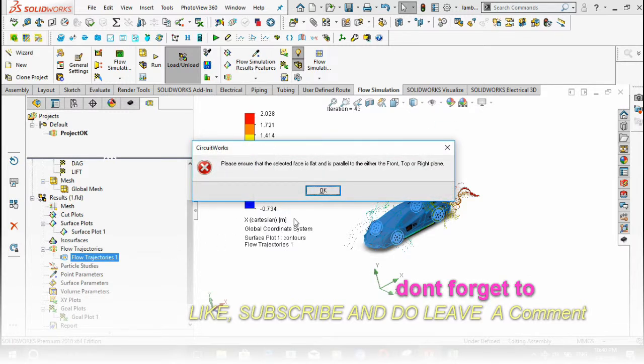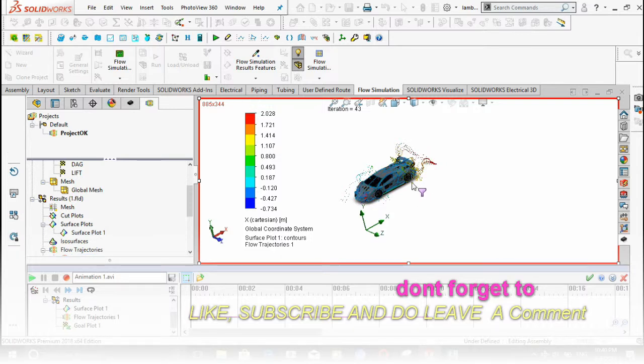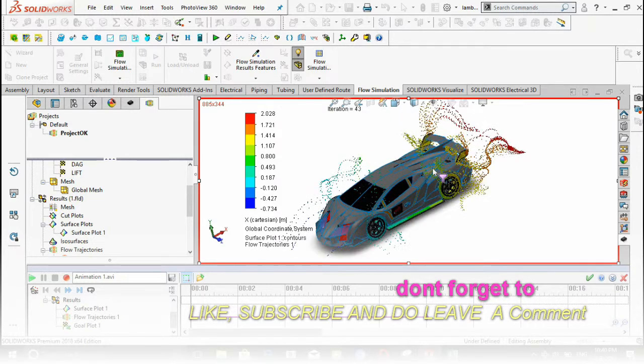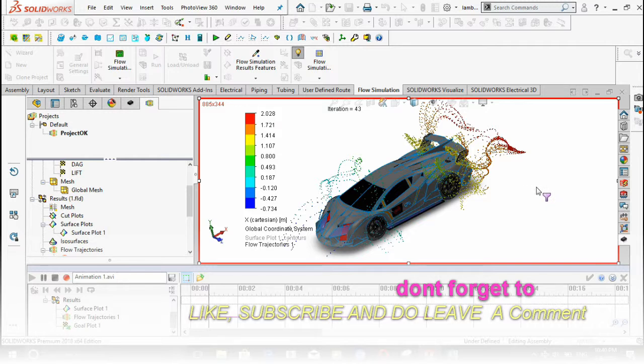So what we are going to do is we are going to go now to flow simulation trajectories. So at a level of flow simulation trajectory, you're going to right click and choose animate. So once we choose animate, this is what you're going to obtain. You're going to obtain something like this. So when I zoom out, I'm going to see that this is it. So I'm going to go to this level and I'm going to animate this. So you discover that once the car is moving, you're going to see how air around it is going to be moving. It's going to be circulating. So this is what we're going to obtain at the end. You're going to see how air that is found around it is going to be moving with it.